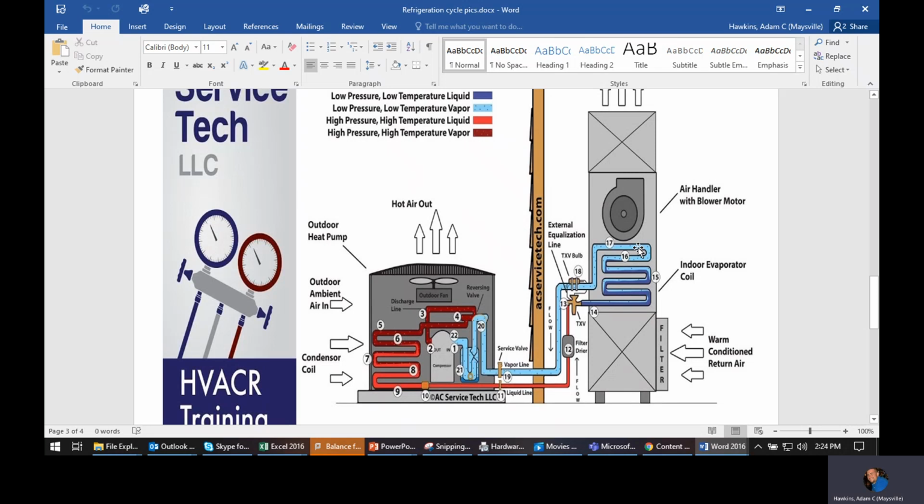So what you're doing is you're heating it up to the point that it's vapor, and then you're heating it up a little bit more. So at this point, the latent is done, which means now we're sensibly heating again. So if you could imagine boiling a pot of water and you were able to capture that steam. Once you boil off all the liquid and you stop the boiling process, all that latent is gone. And now at this point, all the heat that you're adding to that vapor in that container would be superheat. It would be the same for steam. You can superheat steam just the same way. So it's just additional heat beyond the saturation point, or additional heat beyond 100% vapor.